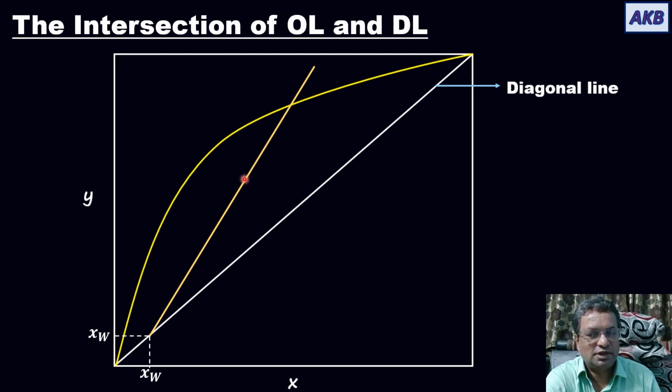Okay, we are going to understand more about how it intersects with the rectifying section line in future videos. I have discussed how to derive the equation of the operating line for the rectifying section in one of my previous videos. So please go and watch that video. Okay, so over here, at the end of the discussion, we have concluded that this operating line for the stripping section of a tray column intersects with the diagonal line at xw.